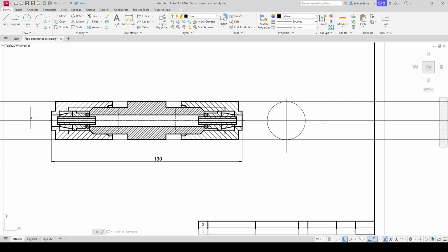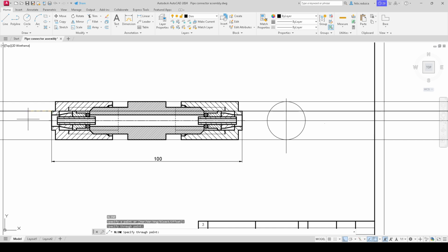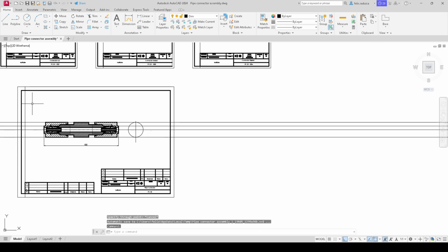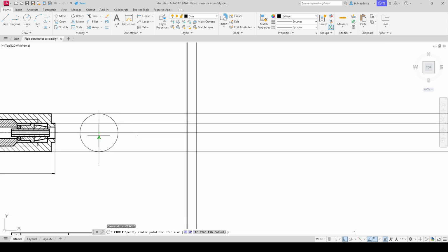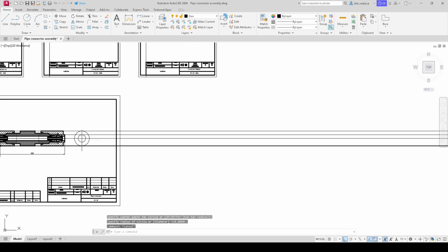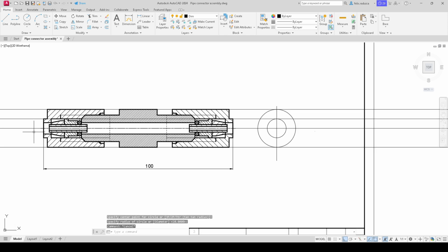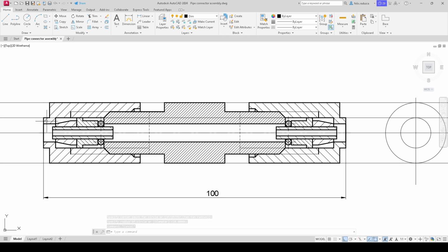We can use the X-line command to help ourselves see where those circles are positioned. So now we can draw another one here. The center is the same, but it's a different position of the edge. So in this case we have another one here with another X line.